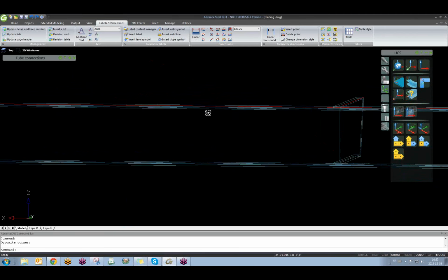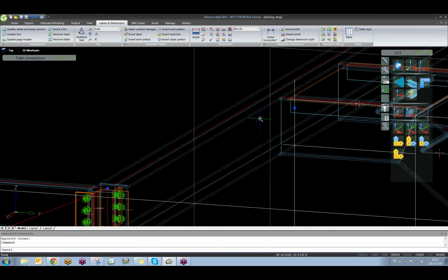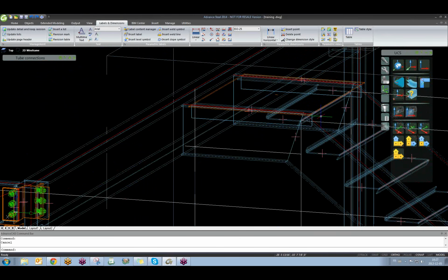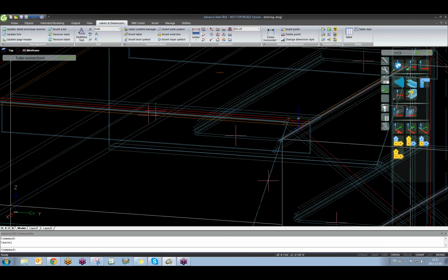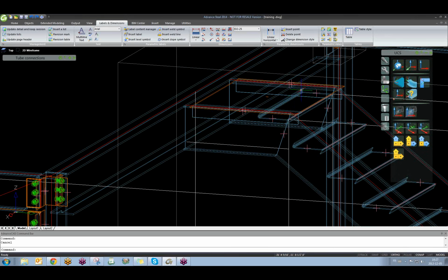I wanted the elevation of the top nosing equal with top of steel all the way around. The top nosing and the top of the stringers and the top of the steel. Oh, so the same elevation. So you don't want the last thread though? Yeah, how do we get rid of that last thread?